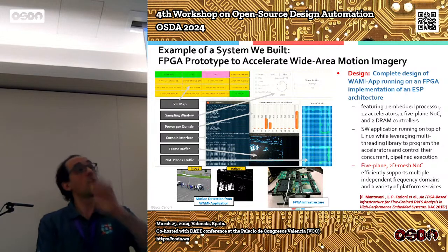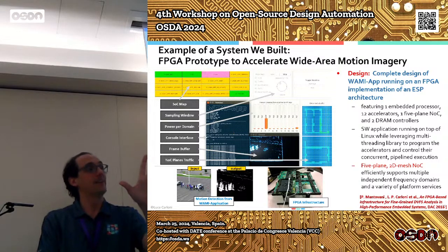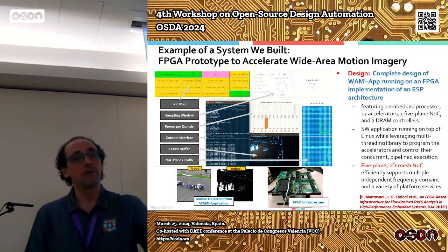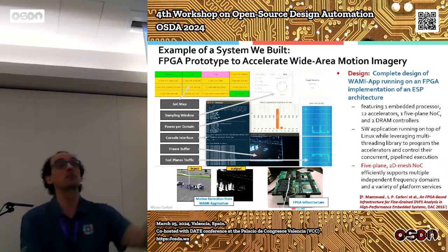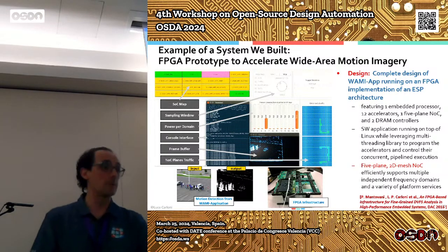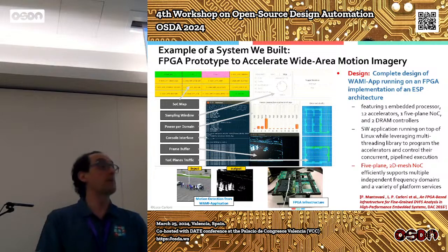You could just say one memory tile or two memory tiles, and of course this increases the bandwidth of the chip. If you double the memory tiles, or you put 4 memory tiles, this reduces the congestion in the NOC, and you can experiment through rapid prototyping. So for many years we focused on FPGA.